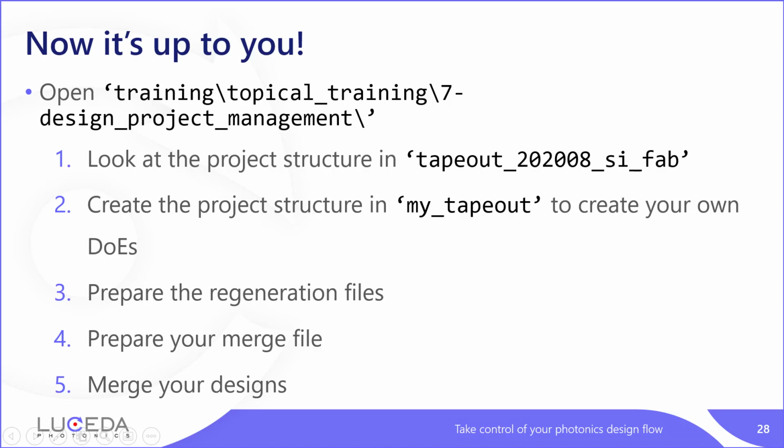Then don't forget to regenerate all the designs, including your own design and the DOE designs from the other designers, including Kiara. And then prepare your merge file to move around the GDS files from your colleagues as well as from yours. And finally, merge your designs.